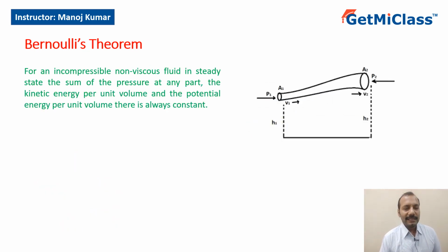The next concept that we are looking into is Bernoulli's theorem. Bernoulli's theorem states that for any incompressible non-viscous fluid in steady state, the sum of the pressure at any part, the kinetic energy per unit volume and the potential energy per unit volume always remains constant. So it is basically conservation of energy in another form.